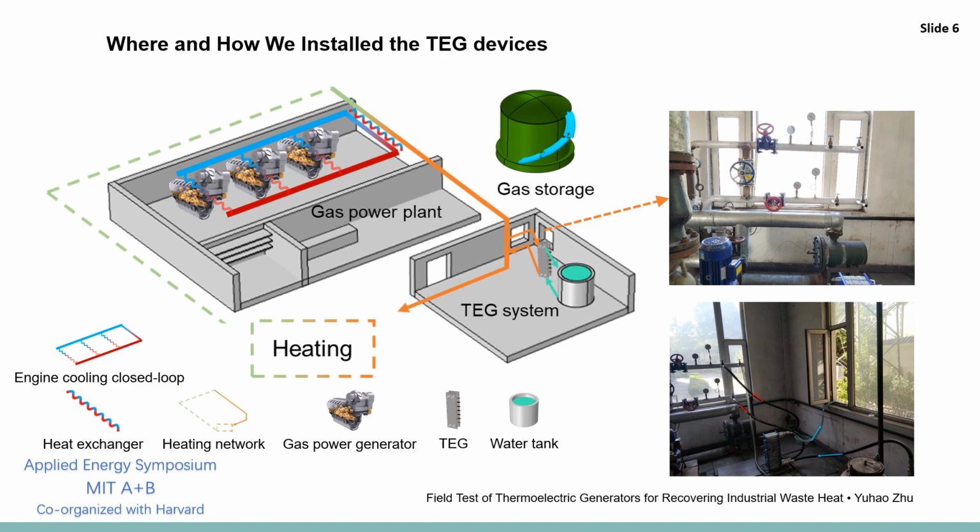To maintain the operating temperature of engines, the inlet temperature of coolant must be kept at 76 to 78 degrees Celsius, and the outlet temperature below 90 degrees Celsius. A large amount of waste heat was carried out by the coolant flowing in the closed loop. Especially in summer, the outlet temperature of coolant could reach 92 to 93 degrees Celsius, close to the shutdown temperature